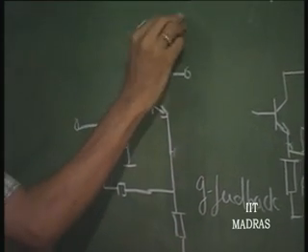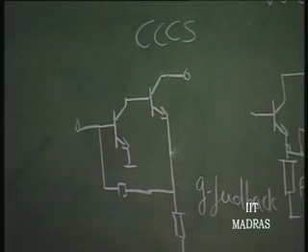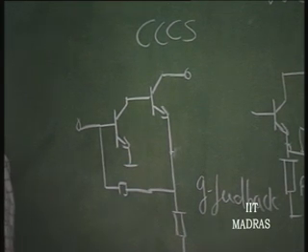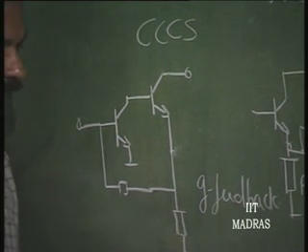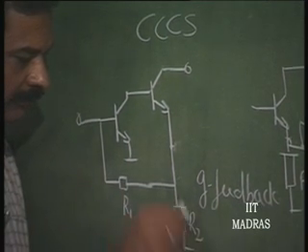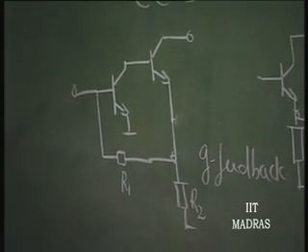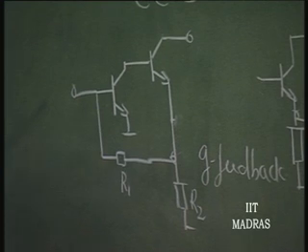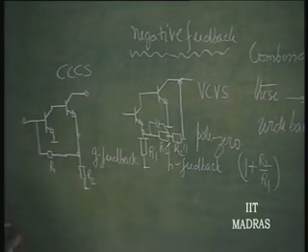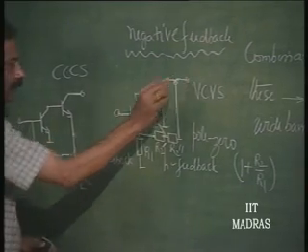This will result in a current controlled current source of the same gain 1 plus R 2 over R 1, and therefore, this also is a wideband amplifier. Again, this might also need the same type of frequency compensation that is given in this case for making it work.